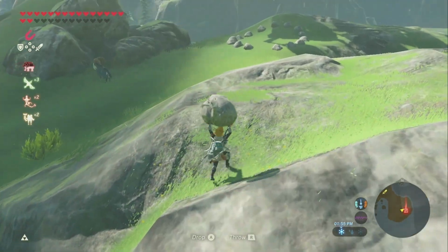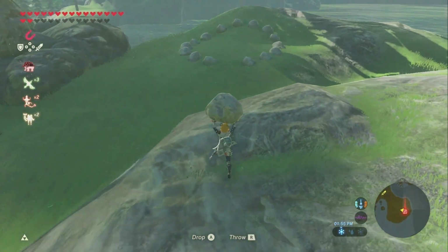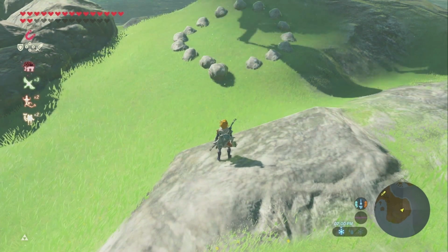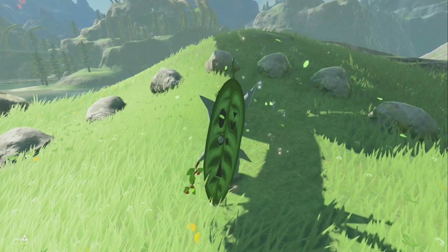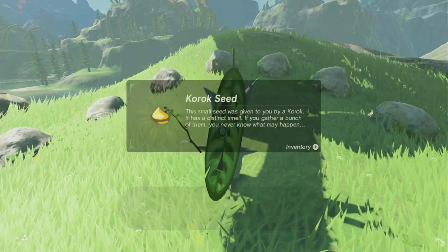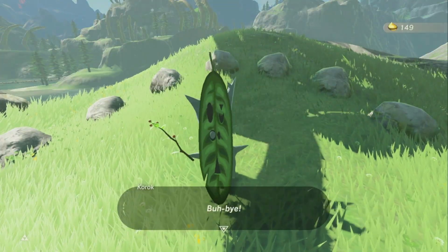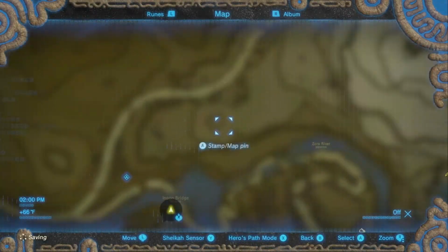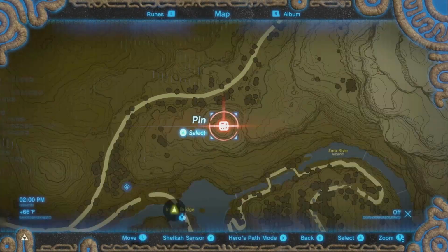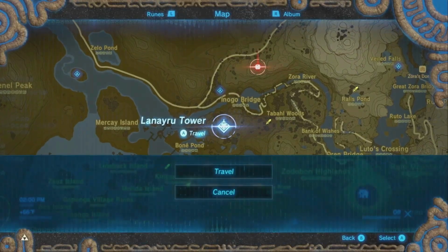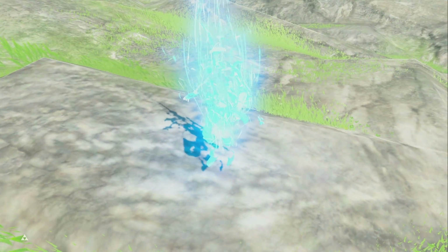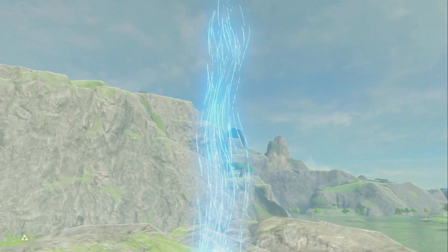Implications. Temperature, pressure relief devices are safety items. If any of these conditions exist, safety may be compromised. Strategy. Check temperature, pressure relief valves, high temperature limits, and pressure relief valves for all of the problems we've listed above. This is equally important on rental water heaters as on owned water heaters. The life safety issues here are significant.